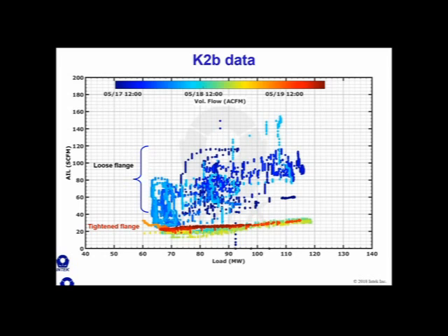The air in-leakage was kind of all over the place because the pressure of that tank varies so widely depending on if something's draining to it or if something's not draining to it. And so that changes the pressure of the tank. Since it's just essentially an orifice across the tank, it pulls in more or less air depending on what's draining into that tank. So during the loose flange time period, the air in-leakage is kind of all over the place. It's high and it's low, it's high and it's low, depending on what the pressure of that tank is.